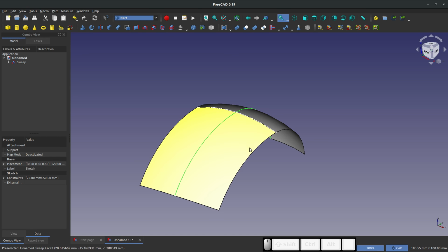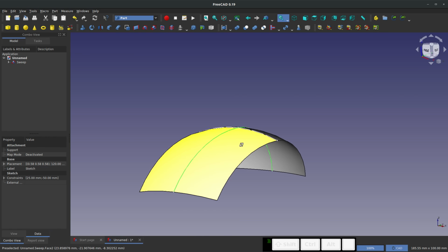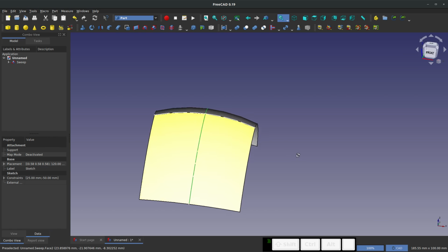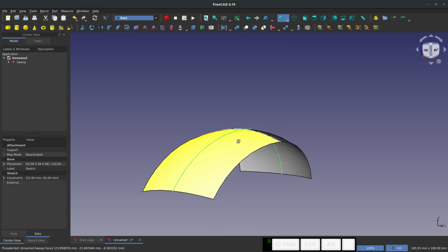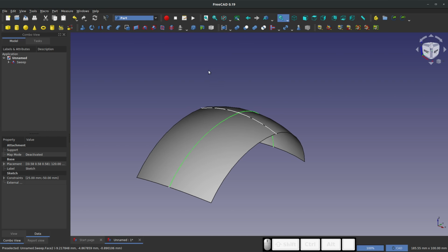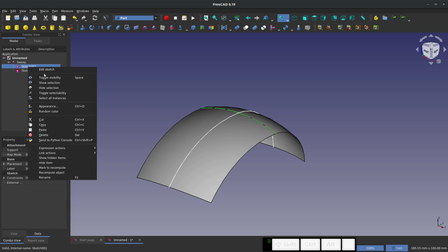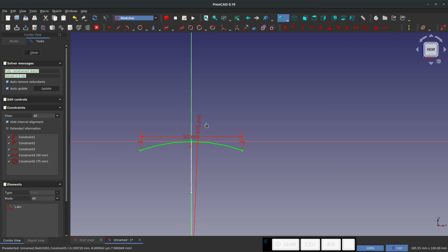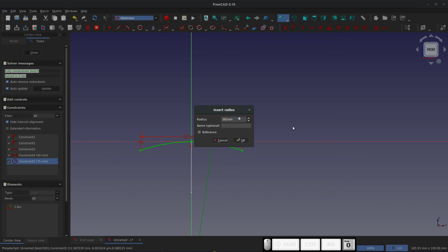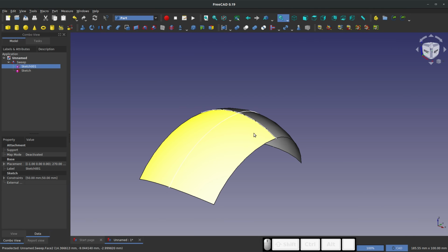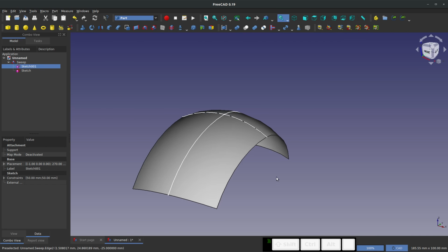and OK. And we don't get a fail to validate broken face, but rather we get this nice surface that is infinitely thin. So one lesson learned is where Part Design generates only solids, Part can generate solids and surfaces. So we take this sweep, and the beauty of this is it's parametric. I would like to actually change this from, how about 75? Let's go down to 50 to really emphasize the curvature better. Close that, and that looks like a nice curvy surface.